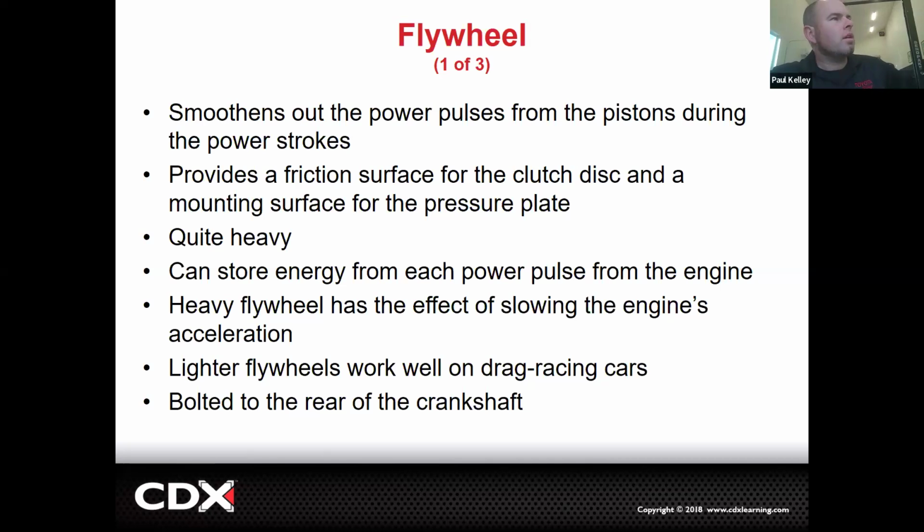Can't have both. Okay, and then it provides a friction surface for the clutch and also a mounting surface for the pressure plate. So that's where the bolt holes are. Makes sense? They should be heavy and can, in a way, store energy in the form of inertia. So it took that kinetic energy, boom, and it went into the flywheel as inertia, which would mean, until we get the next burst of kinetic energy by cylinder number 2 firing, it's storing that energy as inertia. It's got some momentum, in other words, right?